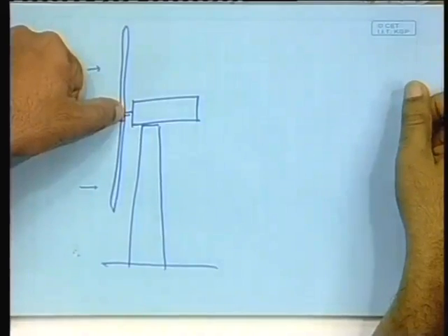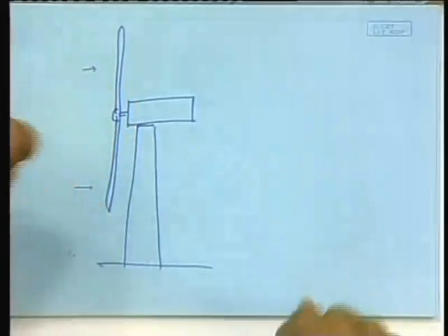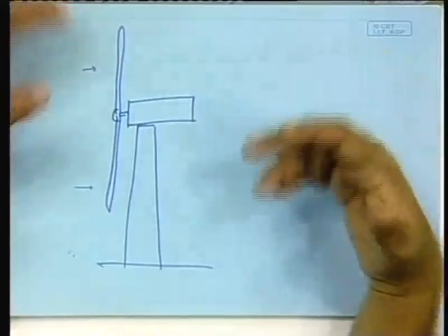As a result, what does this torque pulsation do? The torque pulsation is felt somewhere here. The torque pulsation essentially sometimes leads to blade failures. So, it is generally known that the 3-bladed turbines are structurally stronger, less prone to failure than the 2-bladed turbines.